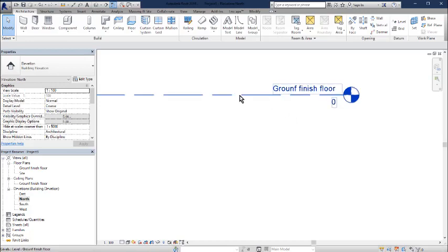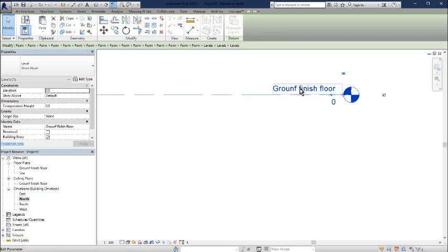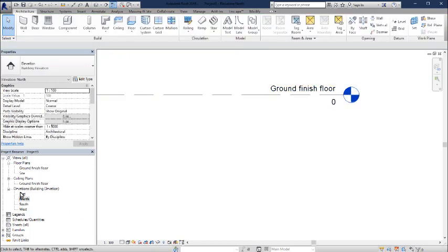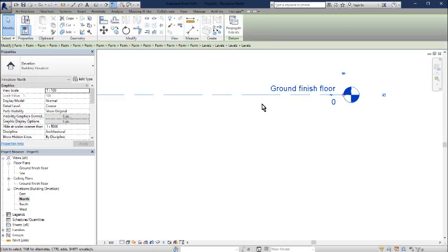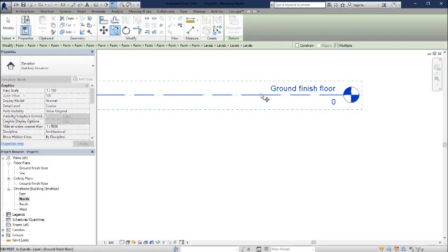Now what we want to do is to have our other levels as what we call empty levels, right? So those levels are just going to be used for referencing, and you won't necessarily see them come on the list of levels that you see in here on your left. So to get empty levels, all we need to do is just copy this level. So we're going to copy this level down, and we're going to go down about the thickness of our floor board, which is going to be about 50 millimeters.